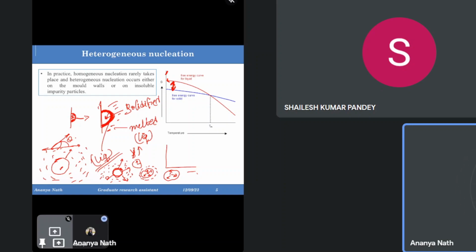This is why Ti is added. The melting temperature of Ti is higher than aluminium. So at the melting temperature of aluminium, Ti will not get melted. It will stay intact in its shape, and the wall of the Ti will provide some support for the new nucleus to grow.